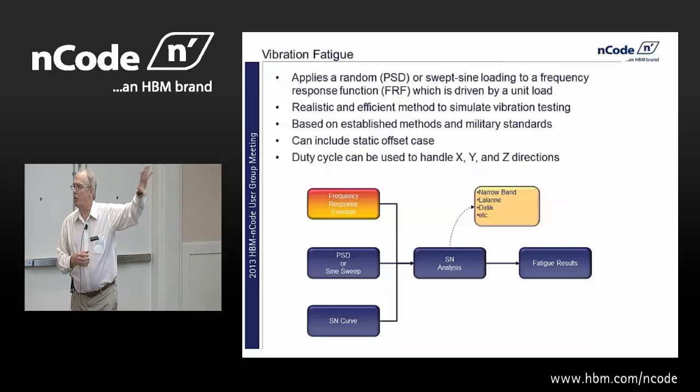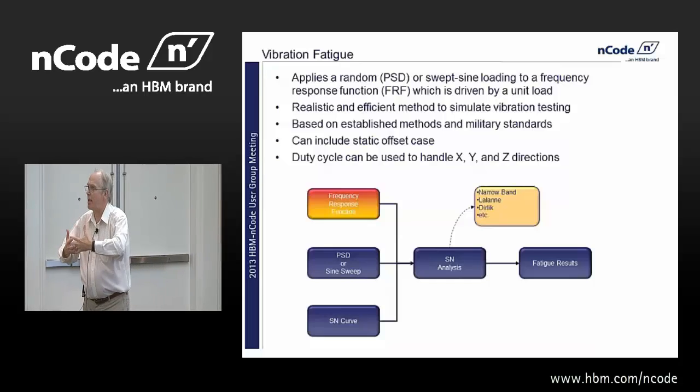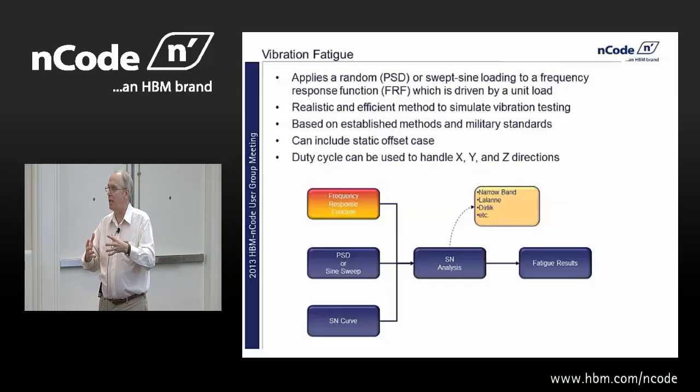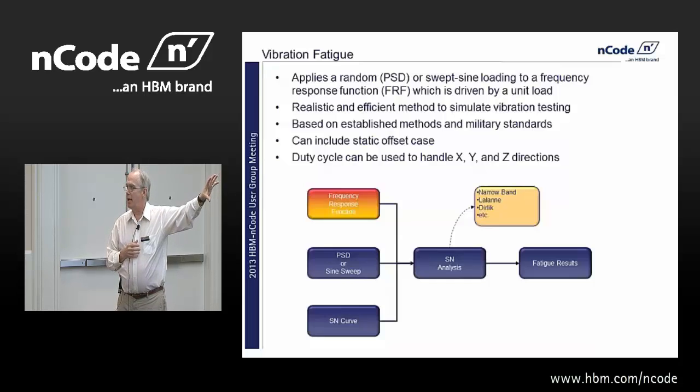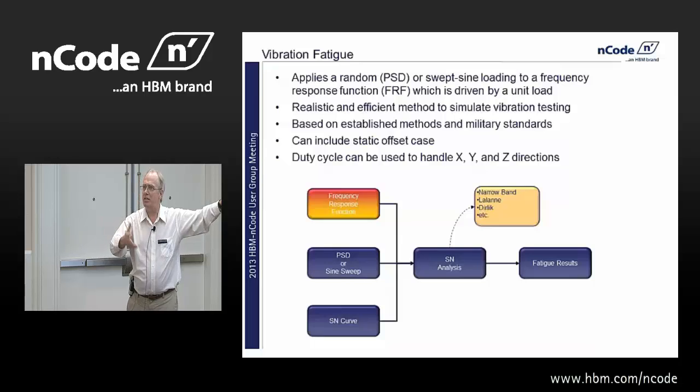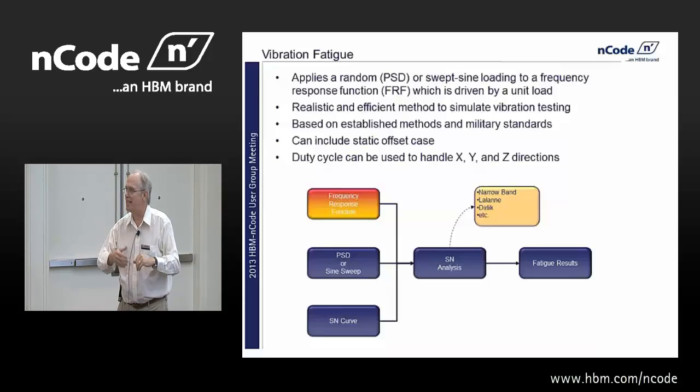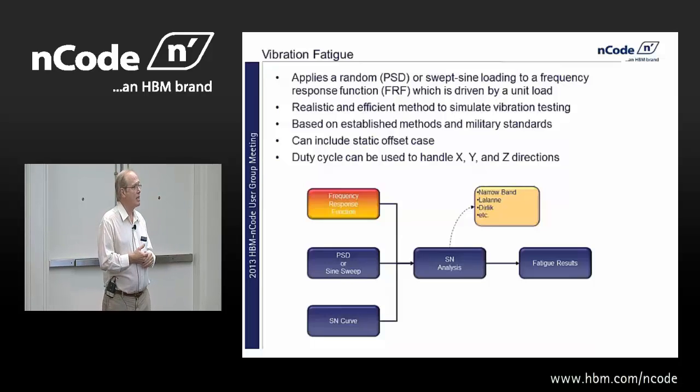Basically, we're going to use the same sort of approach that we use time-based, but now our FE input, instead of being either modal transient or static, is going to be some sort of frequency response. That has different names depending on which analysis code you're using: Solution 111, or steady state dynamics, harmonic. But it's going to look at a frequency response. We'll pair that up with an input PSD. Then inside of DesignLife, we'll generate PSDs of stress to do the fatigue prediction. There are little magic boxes that can look at these PSDs of stress and calculate cycles.